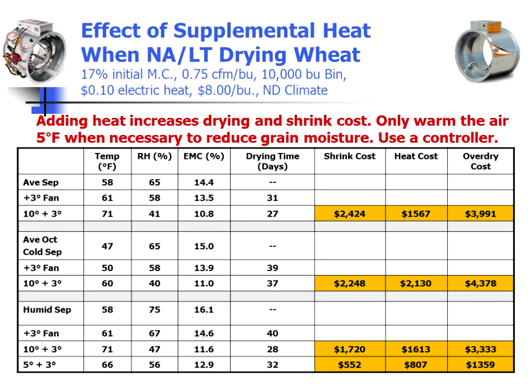And what we frequently will look at is, well, should I just run my natural air drying system, or should I be adding some supplemental heat? And what I normally will tell people is that if we're concerned about drying speed, basically we're looking at airflow, regulating that drying speed. If we're looking at changing the final moisture content of the grain, that's when we start looking at supplemental heat. But one of the challenges that we face, whether we're talking wheat earlier in the season or corn later in the season, is that potential for over-drying.